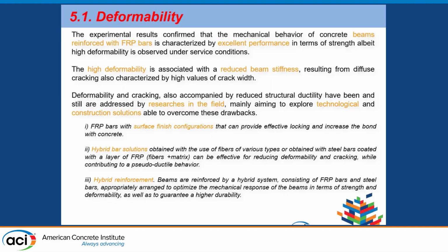So, although there is the contribution of the present work, there are still several issues that must be further analyzed. In general, the experimental results shed light on the fact that in terms of strength, the use of FRP rebar gives a significant contribution. However, some concerns are still there regarding the high deformability observed under service conditions. The high deformability is mainly associated with reduced beam stiffness, which is a result of the diffuse cracking as well as the high value of the crack width.